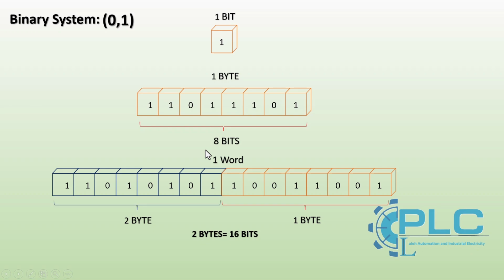In Siemens S7-300 PLCs, inputs, outputs, and memory addresses follow a structured format. Inputs are designated with the prefix I. For example, I0.0, I1.2.